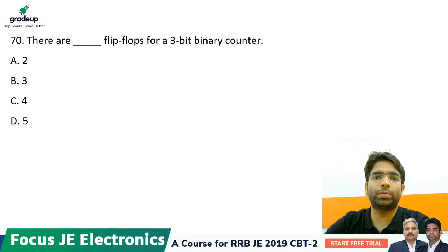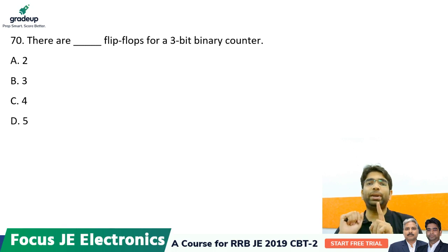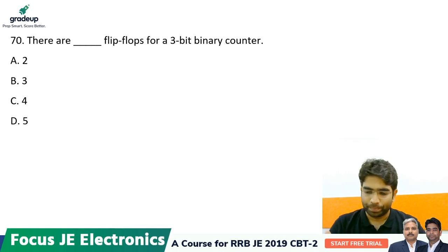There are dash flip-flops in a 3-bit binary counter. My dear friends, please pay attention to this. It is a 3-bit binary counter. It is not a 3-stage binary counter or a mod 3 binary counter. It is a 3-bit binary counter. So 3 flip-flops must be required.